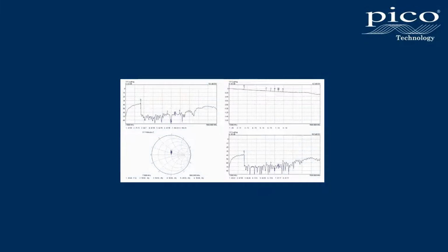As a footnote to this demonstration, I think we have seen here that TRL-TRM calibration results in bands of calibration that each have slightly different Z0. Those Z0s might be very precisely 50 ohm if we are using airline standards, but more likely, if we're using substrate-based standards, they may each be slightly offset from 50 ohm and from each other, and that might be imaginary offset or real offset. In other words, our Smith chart will have slightly different origins for each frequency band: TRM, TRL line 1 and TRL line 2 if we are using two lines.